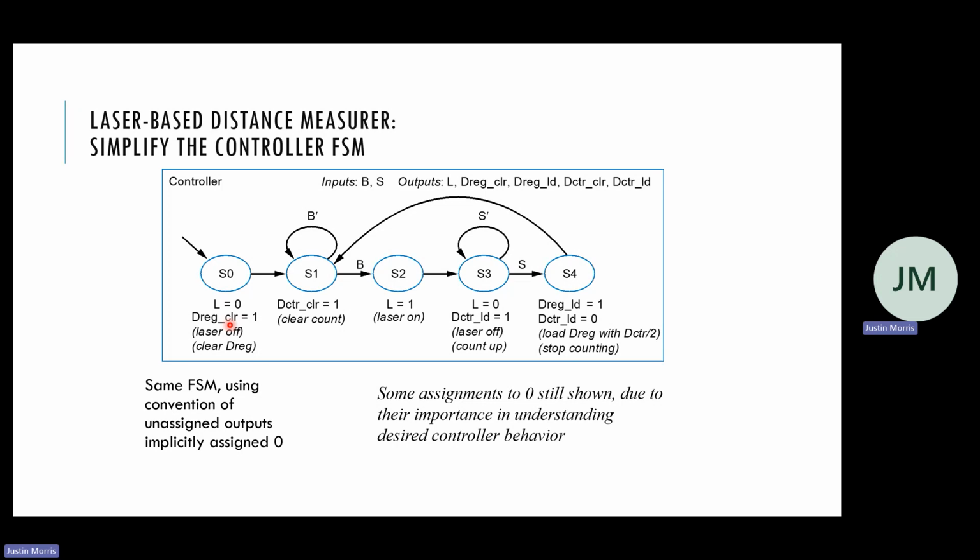Follow up. So then would you have to turn the high-level state machine on and off to be able to use it again? No. Because it gets overwritten next time it goes to S4. Right. So you press the button again, it counts again, and then it overwrites the old measurements in S4. And then you go back here. So it gets calculated in S4. It displays in S1. That one is pressed. The counter clears, but the output register, D-reg, doesn't change again until S4.